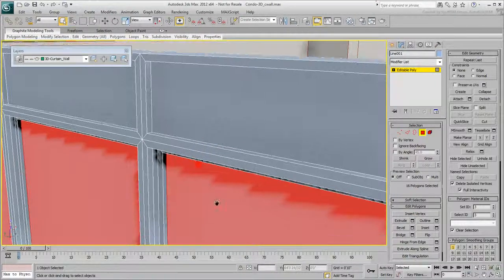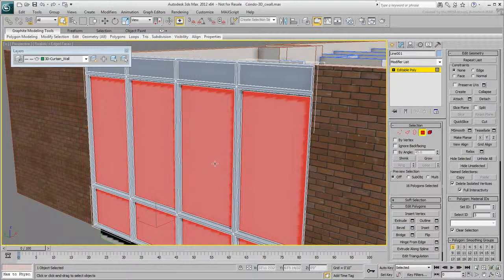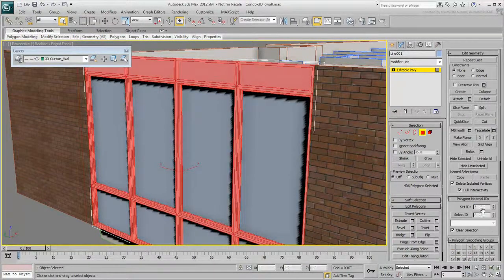on the patio doors earlier. If you recall, the glazing on that material was defined by face ID number 3, so go ahead and set the selected faces to ID number 3. When that is done, choose Edit, Select Invert, and set all remaining faces to ID number 1. If you recall, submaterials 1, 2, 4, and 5 were all instanced with the same bronze-brown, shiny material.